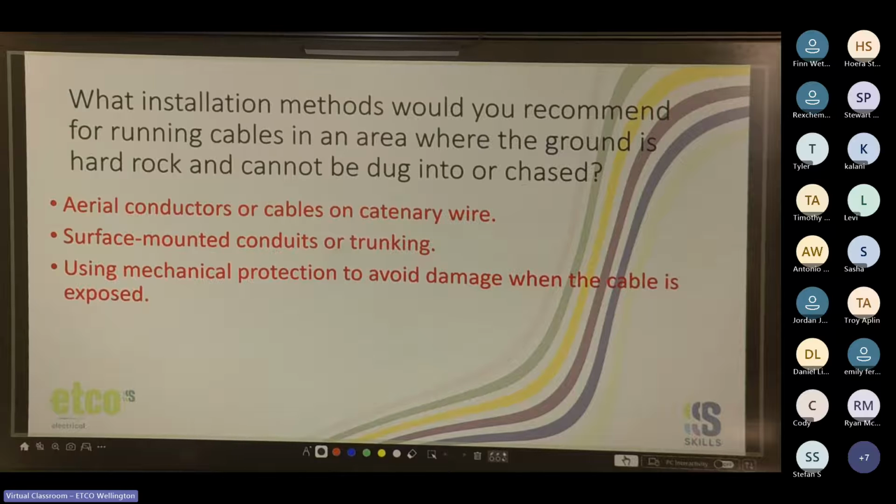Yep. Another thing, like we looked at last week, you can have the cable at a certain depth, and then you could backfill. So you could increase the ground level if you really needed to. You can put your cable down, bury it with so much sand, cover it with more topsoil, and then concrete over the top, and it wouldn't be that much of a height change.